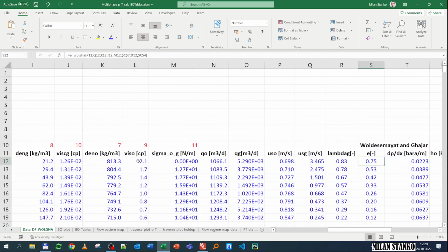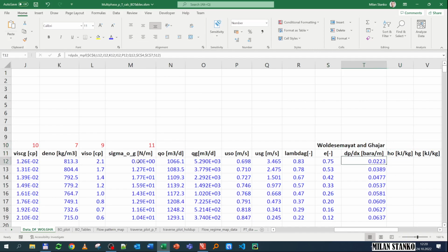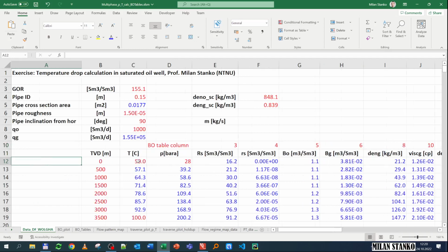We calculated the void fraction with the correlation from these two researchers, and then we calculated the pressure gradient at that position. With that pressure gradient and using an explicit integration, we calculate the pressure at the point 500 meters below by saying that it is the pressure 500 meters above plus the pressure gradient times the distance. The pressure gradient was calculated using the drift flux model and neglecting the acceleration pressure term.